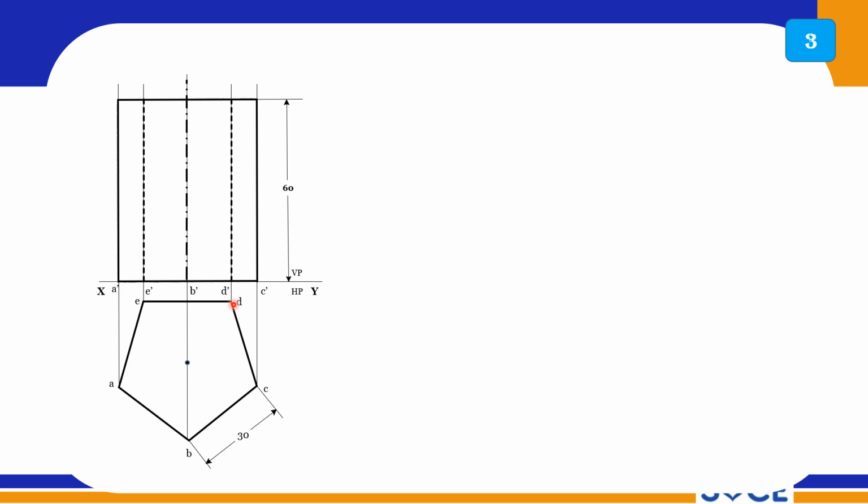So now it is cut by a plane, it is at 35 mm from the base, and it is making 35 degrees to HP. And similarly the view points. So here it is cutting all the lateral edges, all lateral edges are cut here. So this is my 1, and 2 is on B, and 3 is on C, 4 is on D, and 5 is on E. So there is no problem, you can easily develop it.